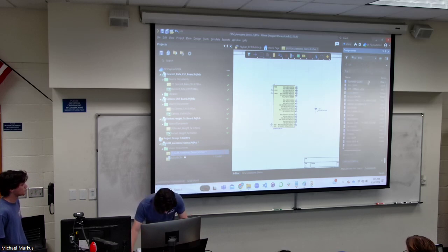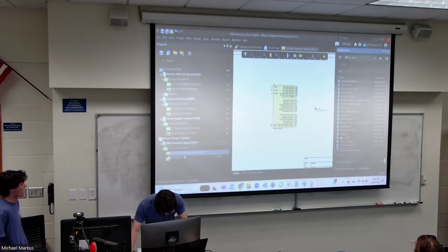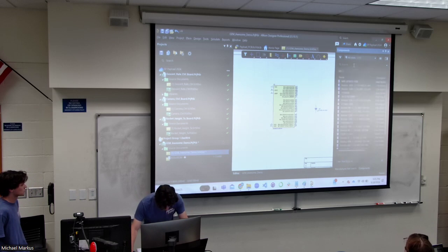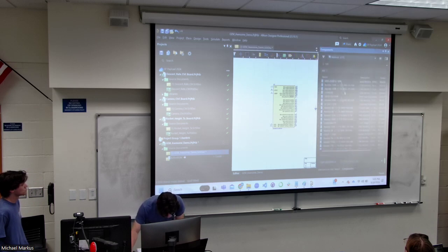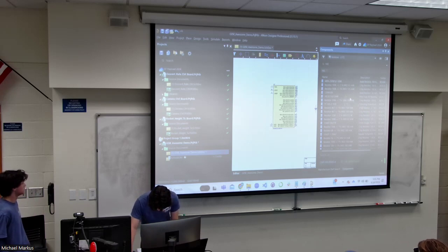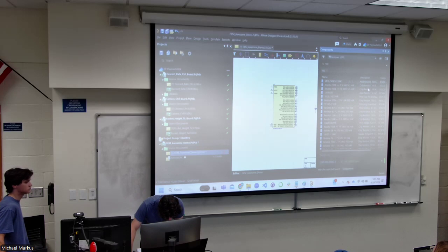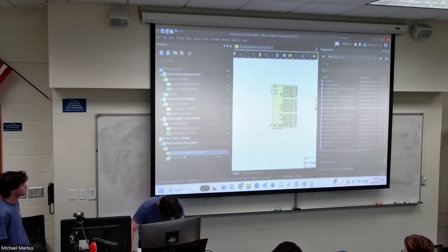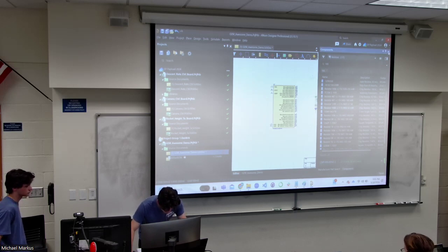Okay, so then we need a resistor for the LED so it knows how much current it needs. I'm going to go with a 100 ohm resistor. There should be some options in here. Let me go to resistors, 100, and this should give some 100 ohm options. Where's a 100 ohm option? Okay, here's a 100 ohm option. You could probably search 100 ohm resistor, and something similar will come up. So we have our resistor.